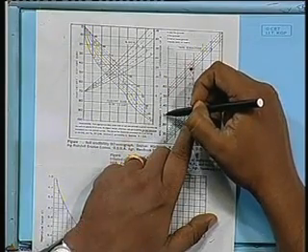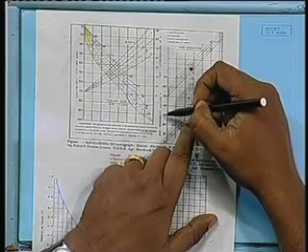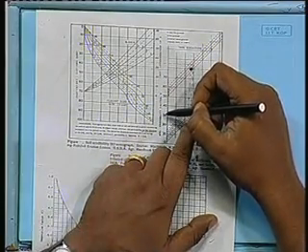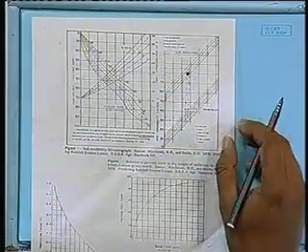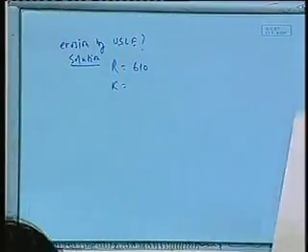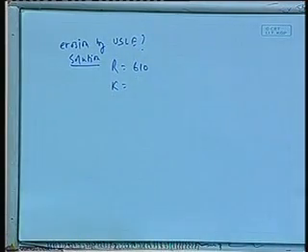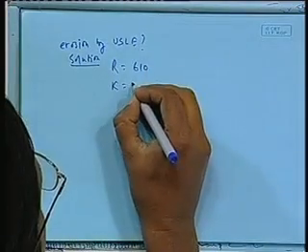So this is the value of K that we have to accept. The corrected value of K has to be accepted. This is called the soil erodibility factor that we will find out. You will also find out the value of K. So the soil erodibility factor that we have found here is about 0.29.